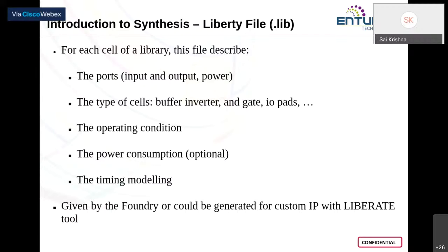So that is your first input, RTL code. Now the second input is your .liberty file. As I earlier told you, the liberty file contains all the functionality related information. Whenever I say functionality, I am actually referring to handling signals. How a design is handling the signals. That is what I always refer to.